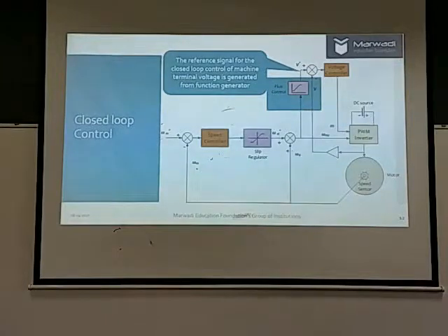Okay. Now as we can see, the speed is sensed through a mechanical sensor. There is a closed loop. The PI controller provides the maximum slip, and then the mechanical speed is added in the summing block, which gives us the ωms.